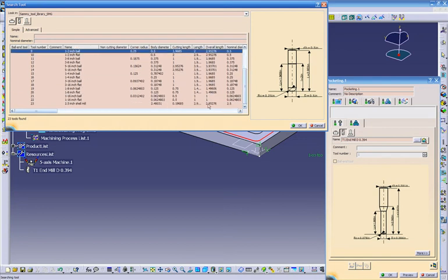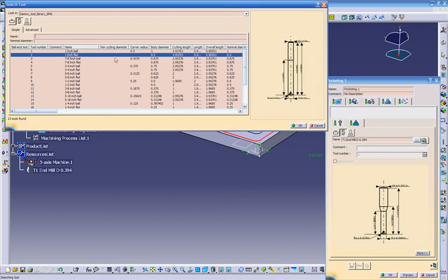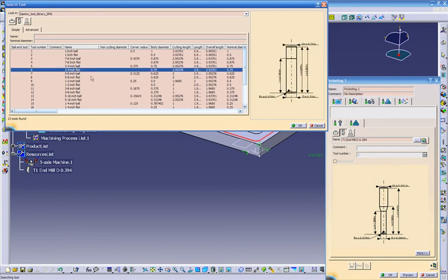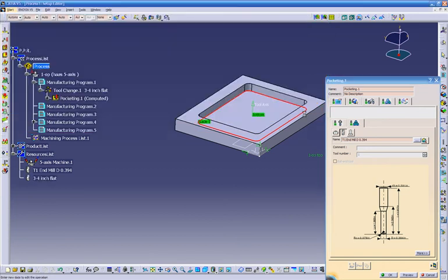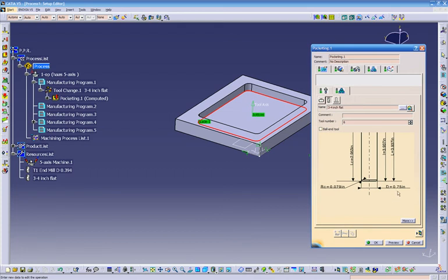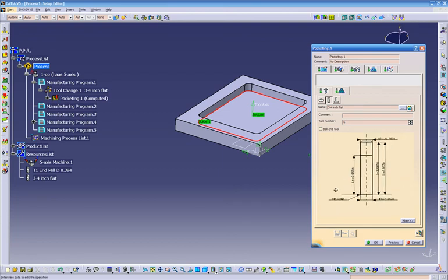This is standard diameters. And for example, let's say we want to choose a 1 inch flat. Let's click on 1 inch. 1 inch ball. 3/4 flat. Click OK. And you can customize it. Even though I said it's a 750, for some reason it puts this radius in here, but you can double click on it and make it 0, make it a sharp corner. And you get your tool over here, customize.